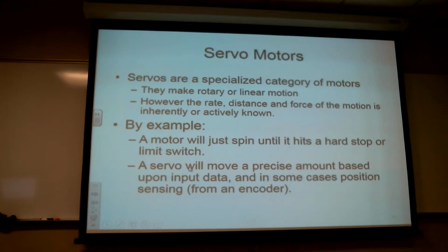You still have to reference 0, but versus the laser cutter right there, its big stepper or servo motors do not have an encoder. First thing you do is turn it on, get everything running, and then tell it to go home. And it goes boom, and finds home. The next thing you do is set depth to meet the right focal length. And every time you turn it on or reset it, you've got to do that.